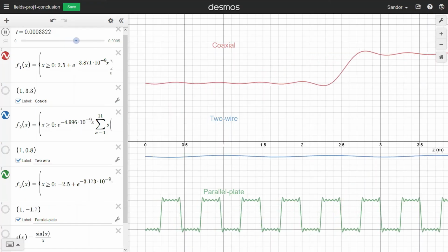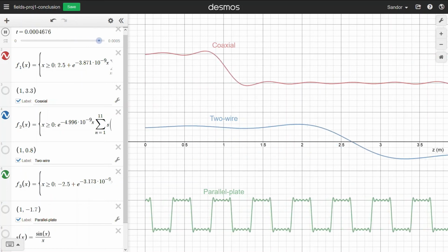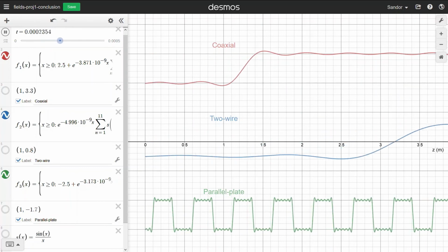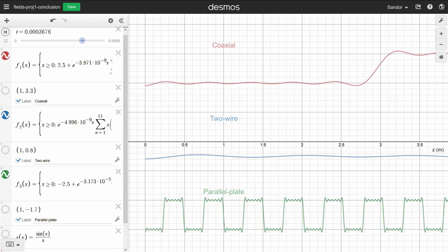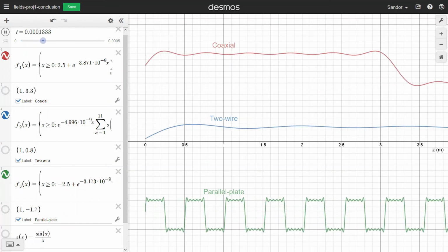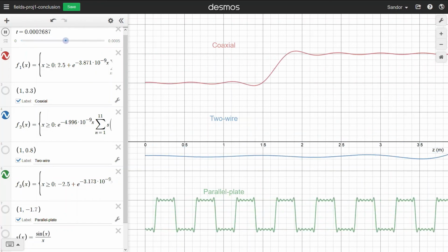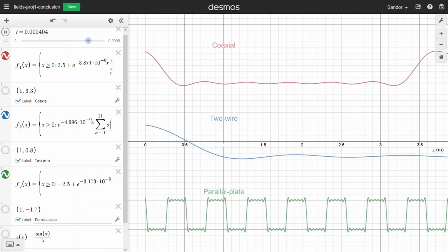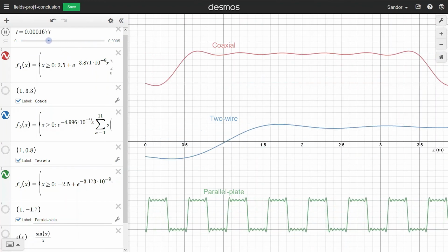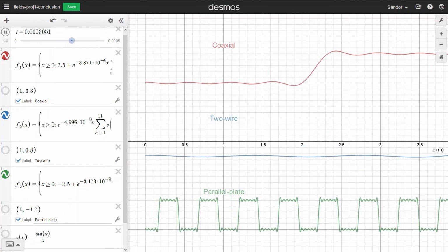With the Heaviside condition implemented, the square waves look like this on the 3 transmission lines. They all have the same frequency, but their wavelengths and phase velocities are different because of T-line parameters. Because of the huge amount of inductance we added, alpha is much smaller and beta much larger than before. This is why the wavelengths are only a few meters now rather than tens of kilometers. So now that we've eliminated distortion, everyone's happy.